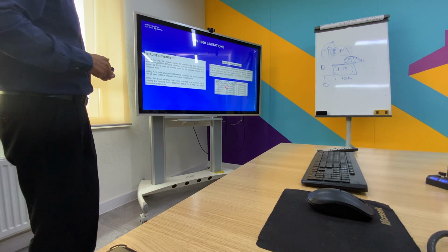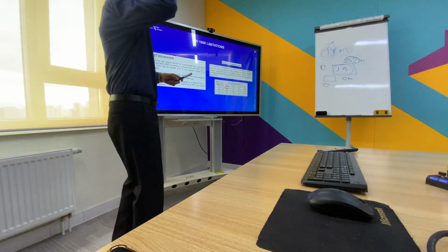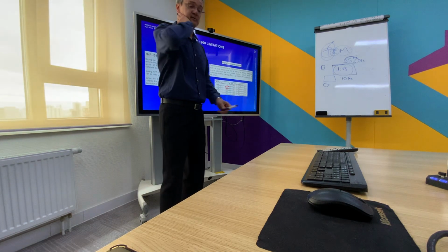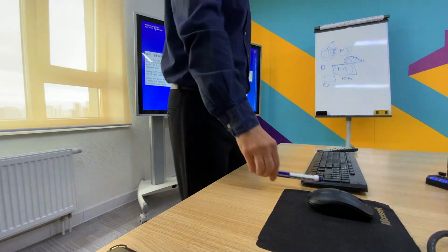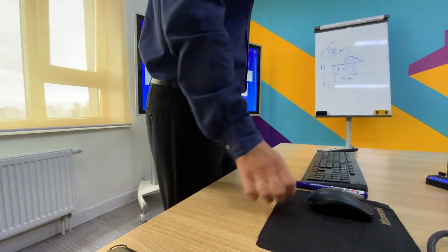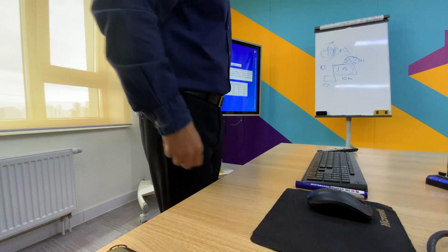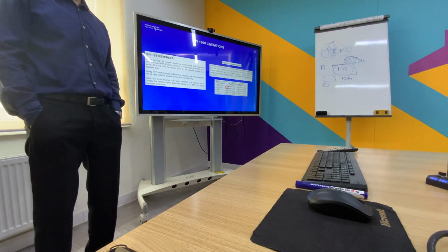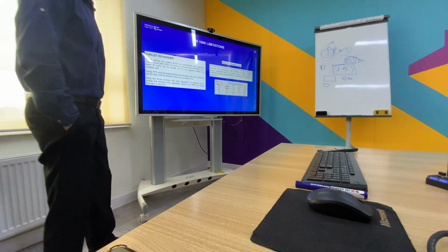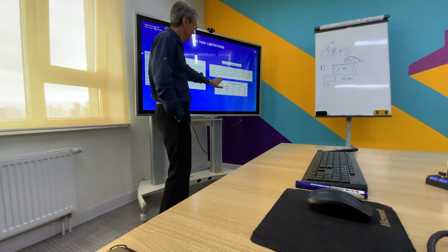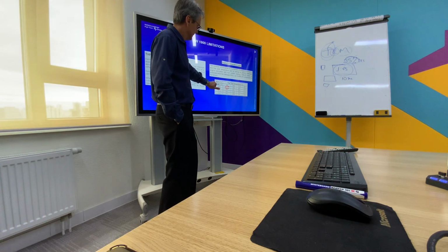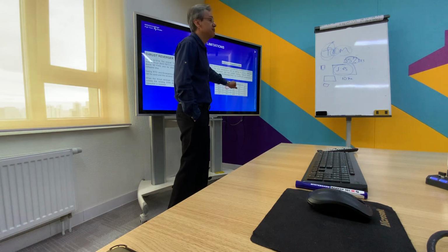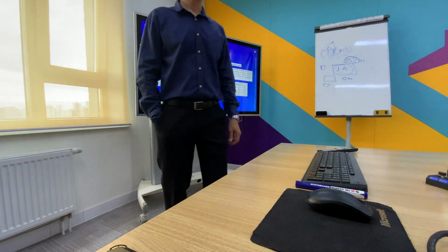We have a limitation for the oil temperature. We have this message on the ICAS. It's written in the AOM that the oil temperature must be above 49 degrees. But in fact, this temperature is based on the outside temperature and the fuel tank temperature.